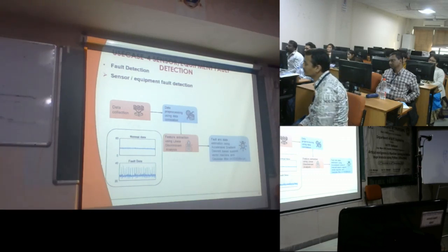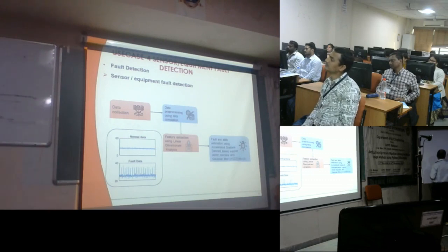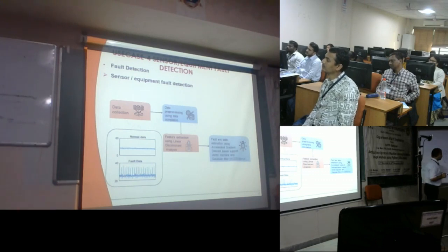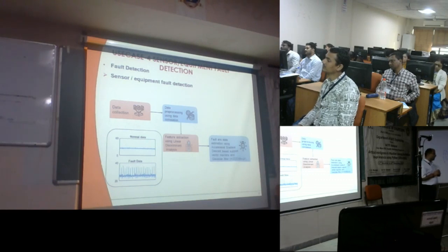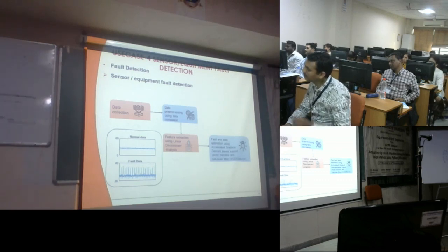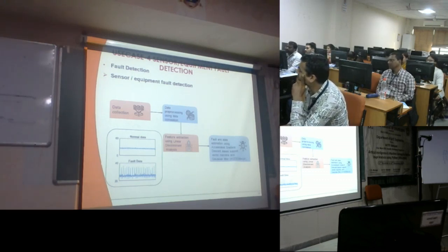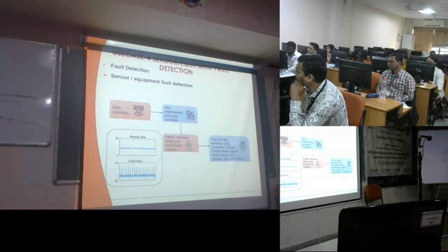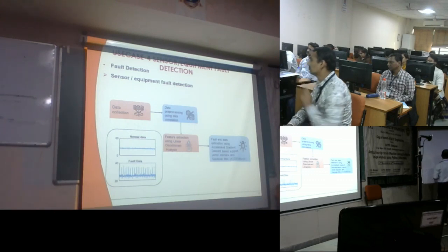So what I can do, I can introduce one more sensor S3, and suppose it is giving T2. Then I can apply the maximum voting logic and see 2 out of 3. The 2 are giving T2, so this is the actual value, and I can ignore the other one, right? So this is known as triplicated logic. So generally we use the triplicated logic.